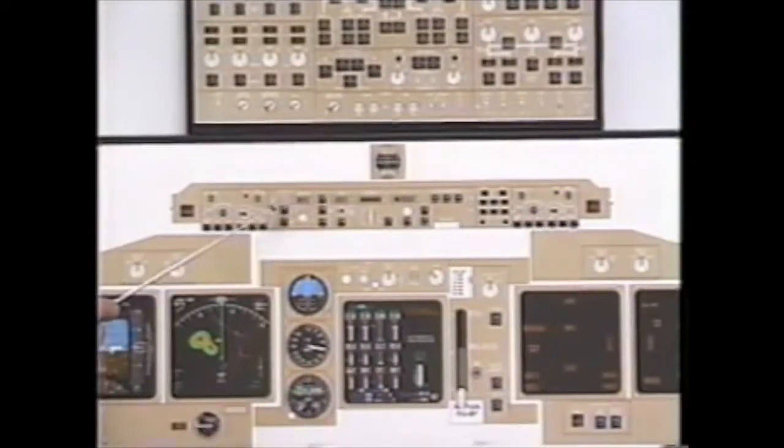Autothrottles have the ability to go after a thrust setting or a speed. The pitch mode of the airplane basically determines which mode of the autothrottles they should be in, thrust or speed. You can use autothrottles without the autopilot and flight director. Thus, you have to reach up and tell the autothrottles which mode you prefer them in, thrust or speed.